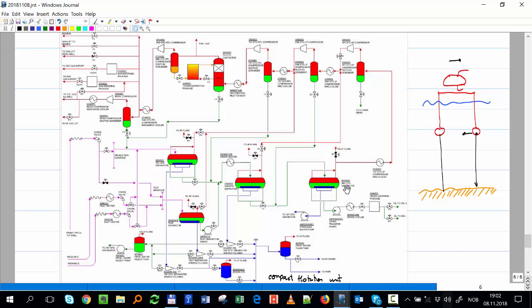Now what is left is the most complicated, always, which is the gas. Let's follow maybe the gas from the high pressure. You have two ways. One, it goes to flare, and that's normally when I have an emergency, like an overpressure. I always have a relief valve, and that goes to the flare.